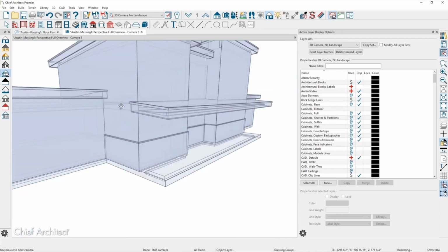So you could draw and expose a few beams in that design and have them poke out and then align your roof so that it would bear on those beams. If you don't want to draw beams, you could also just draw a solid. I use solids for those columns and then just draw it in an elevation view and have it appear that that's a beam that's coming out to cantilever support that roof. Are there tools specifically for drawing beams like that?